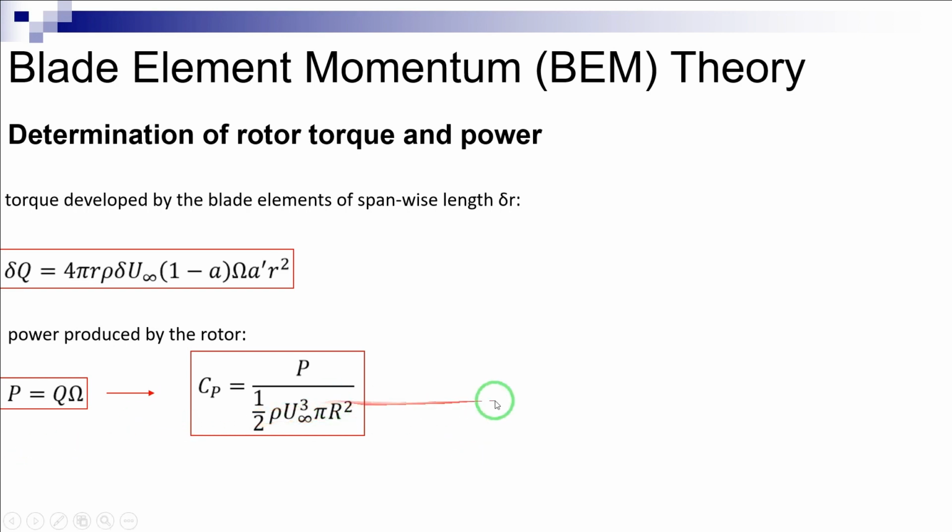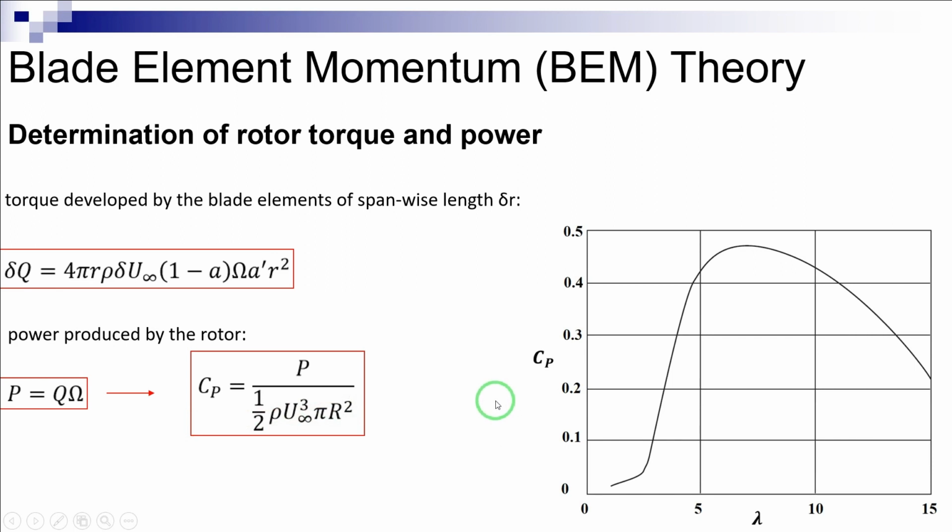A typical performance curve for a modern high-speed wind turbine is shown in this figure. The maximum power coefficient occurs at a tip speed ratio for which the axial flow induction factor is close to the Lanchester-Betz limit value of 1/3. At small values of tip speed ratios, the airfoil angles of attack are high, leading to stalled conditions. Stalling is much more probable over the blade root because, from practical constraints, the twist angle of a blade is not large enough over that region.